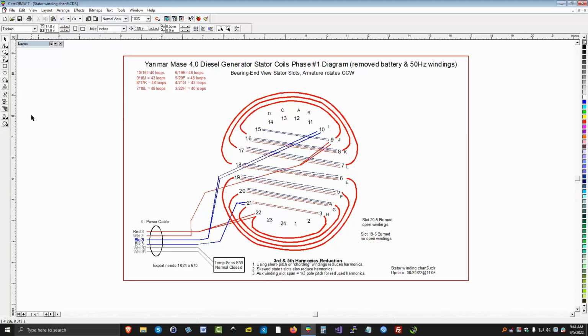Okay, let's talk about some constraints for a moment. Let's say I want to draw a line right here. So I click to start it. I click to end it, but I want it perfectly horizontal. I don't want it off. Well, I want it perfectly horizontal. If you hold the control key while you're in the act of moving the second point, it will force you within limits. Right now it's set for 15-degree limits, I believe.